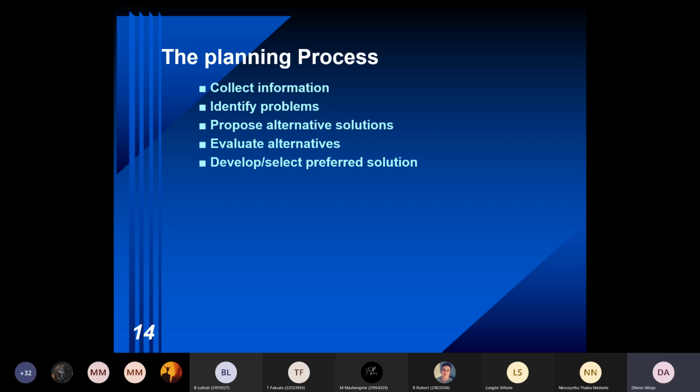Allow X amount of time for vehicles to turn right, stop the oncoming traffic. You travel on roads, so you've seen these arrows. That way you can clear the backlog at that intersection. This falls under traffic management techniques, where you simply readjust the traffic signal setting at that intersection and you can solve the problem.